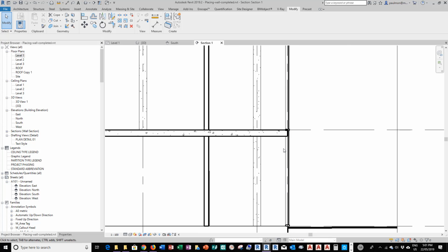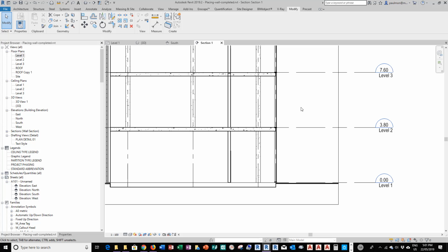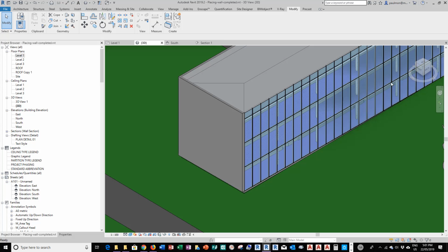And now we need to set up another set of mullions here so we can turn this segment of the curtain system to be spandrel panel, and then we can have the ceiling across this. Now we're going to toggle back to 3D view and look at the curtain panel from an elevation perspective and modify it from that perspective.